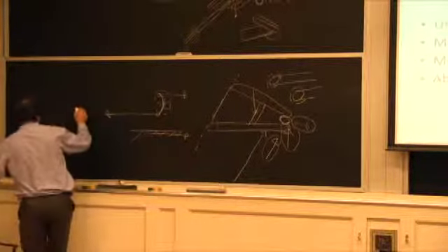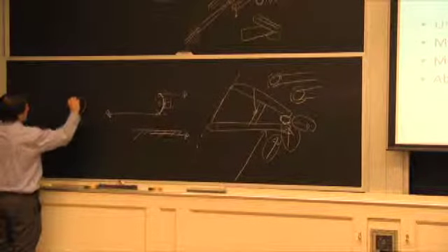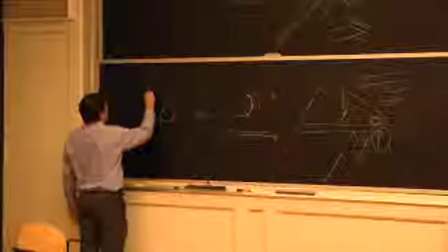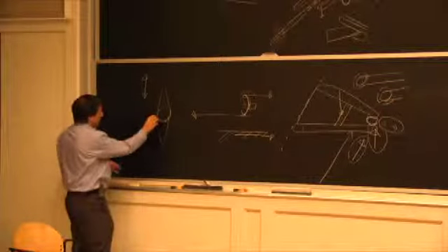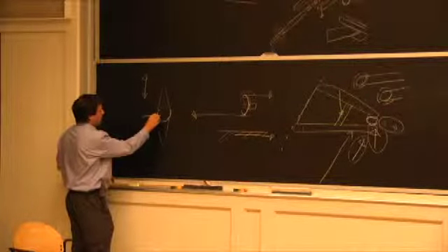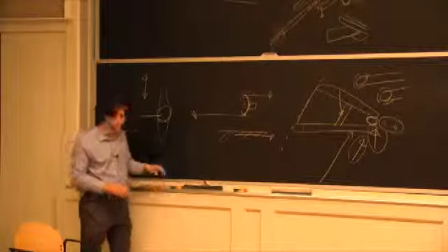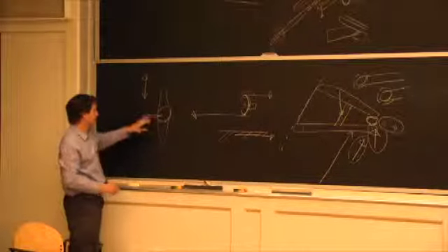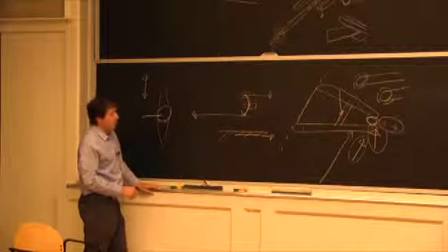So, these were rounded holes. One way we thought we could go is just to elongate these holes in this shape. That would be for loading this way. So we don't have as much of a stress riser at this location. Professor Eager talked about a factor of 3 here. We can take it down to 2.5, and that's for elasticity. When you get to plasticity, the stress concentration factor is less. But anyway, we could work on that geometry.